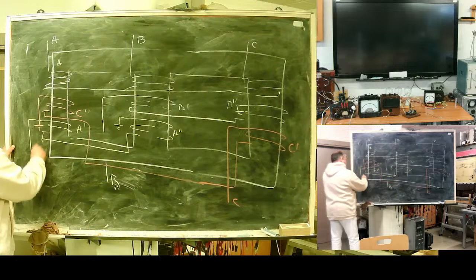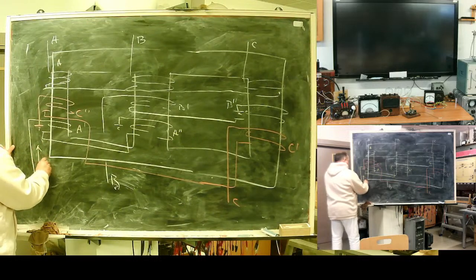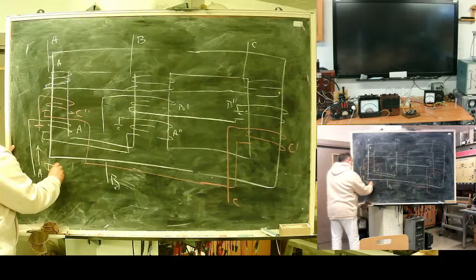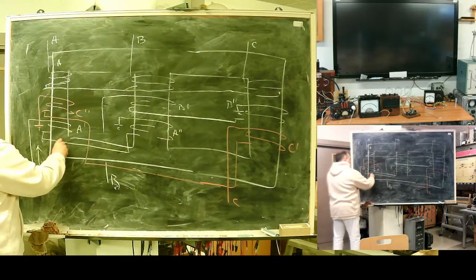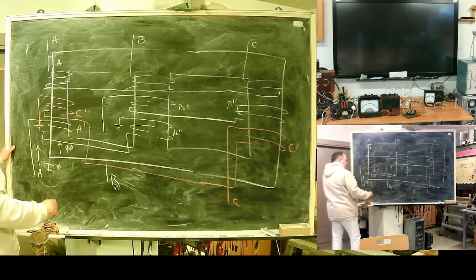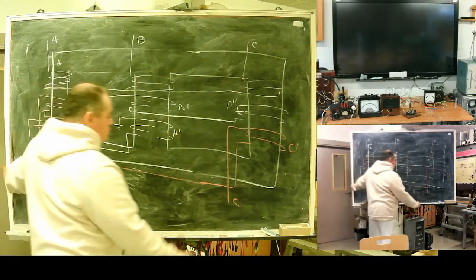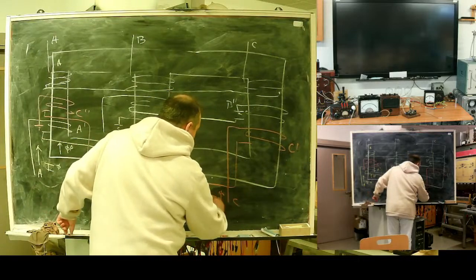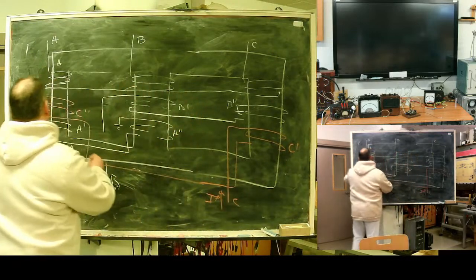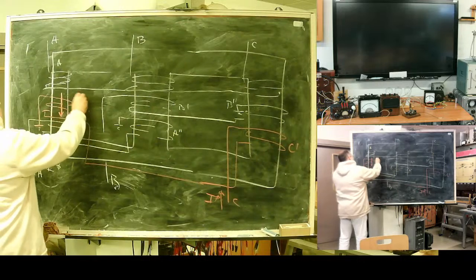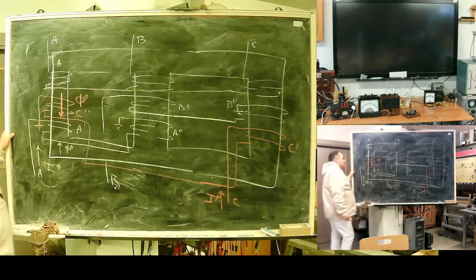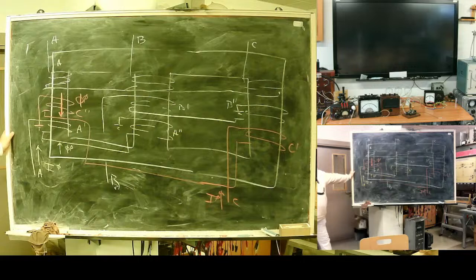In case we have, let's say, zero sequence current and zero sequence flux, the same zero sequence currents inflow here, and we will have opposite zero sequence flux. These two fluxes are eliminating one another.